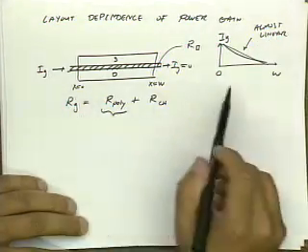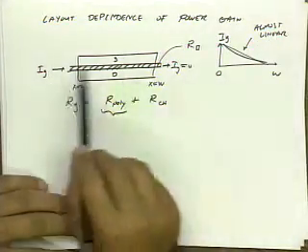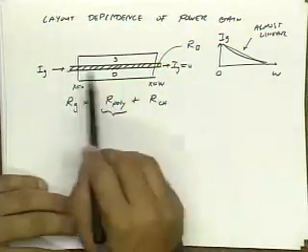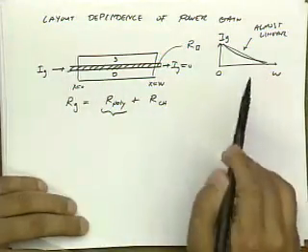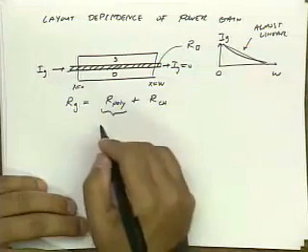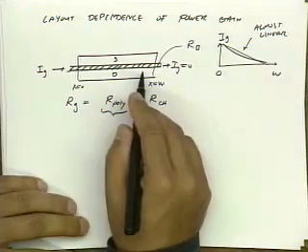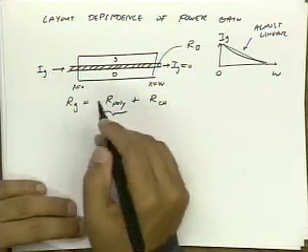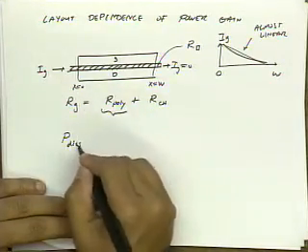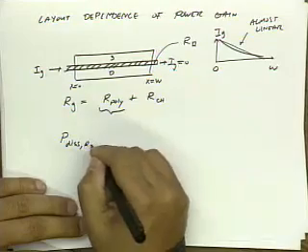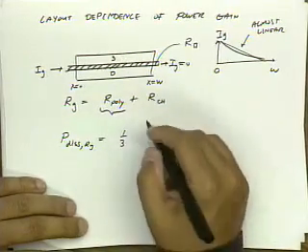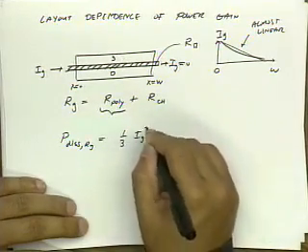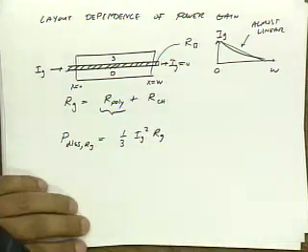Now if you calculate the power loss to this piece of wire, this polysilicon, if you put in a linear current like this, you'll verify that the power loss goes like 1/3 of Ig squared times R. So the power dissipated in Rg is 1/3 I gate squared Rg.